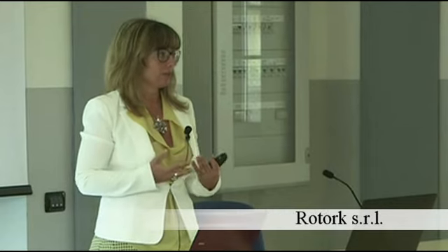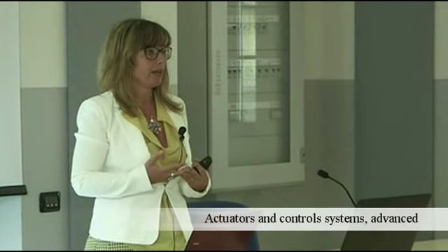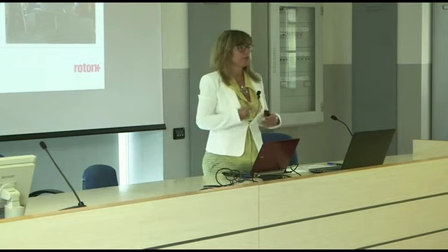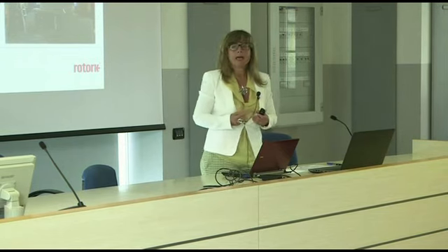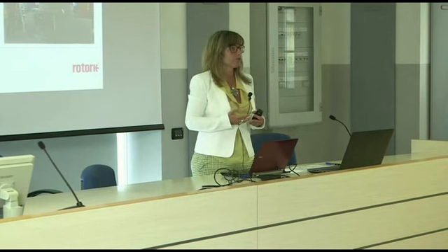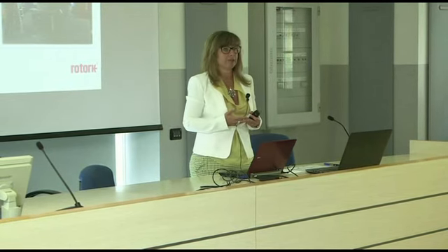The main advantage of a fluid power actuator is the capability to deliver torque or thrust at a very high level, so we can move extremely big valves like the one you can see there in the picture without the use of any gearboxes. And especially when we use a fluid power actuator, we can be extremely fast.